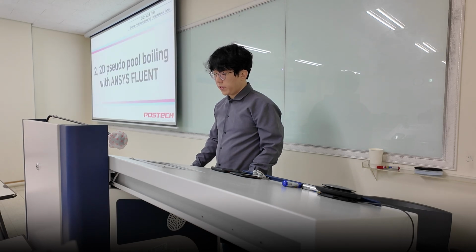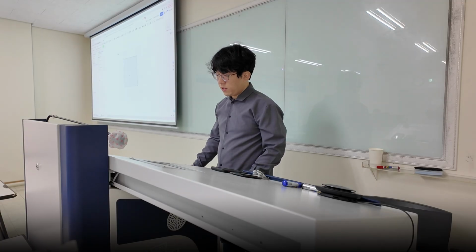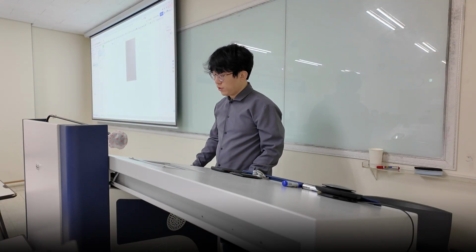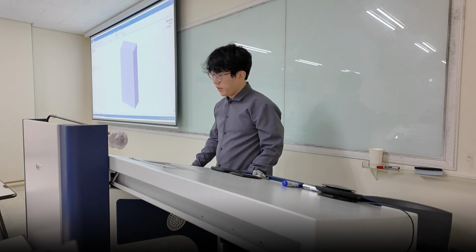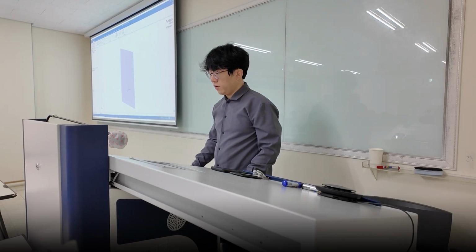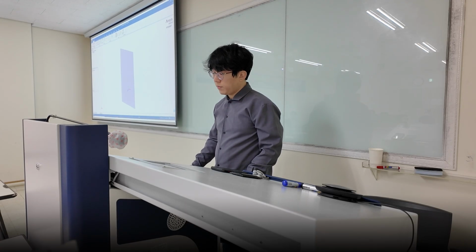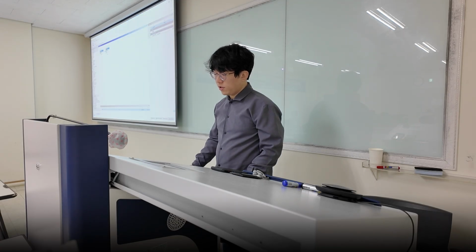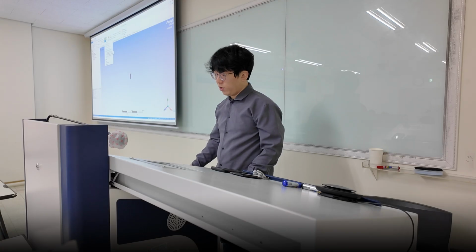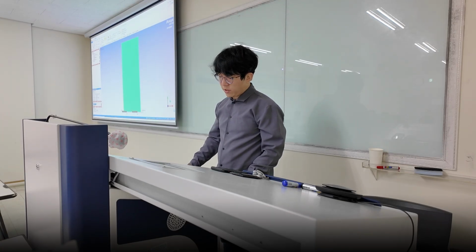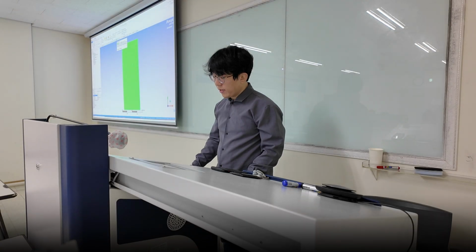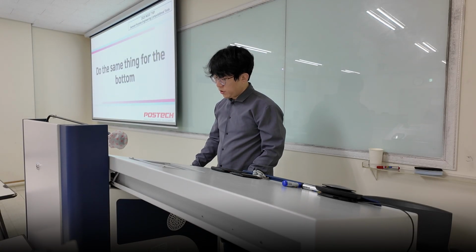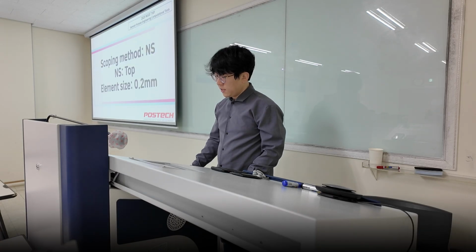The second tutorial will be pool boiling with ANSYS Fluent. You're going to create a two-dimensional sketch, and then create one solid body. Out of the solid body, you're going to take the face, so it's in 2-dimension, and then drag it to the origin, and then use the ANSYS meshing so that it has a progressively refined mesh over the surface. So you can see.